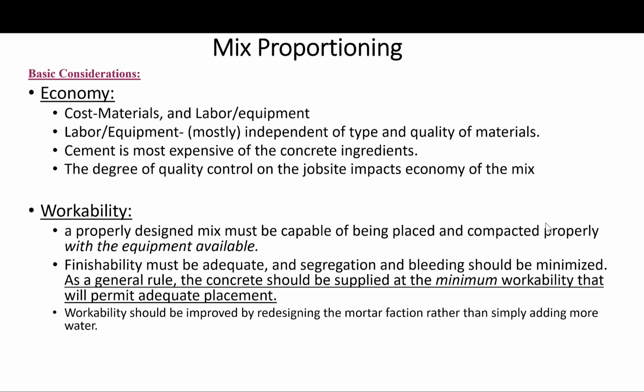Since cement is much more expensive than aggregate, it is clear that minimizing the cement content is the most important single factor in reducing concrete costs. This can in general be done by using the lowest slump that will permit adequate placement, by using the largest practical maximum size aggregate, by using the optimum ratio of coarse to fine aggregates, and when necessary by using appropriate admixtures to improve workability.